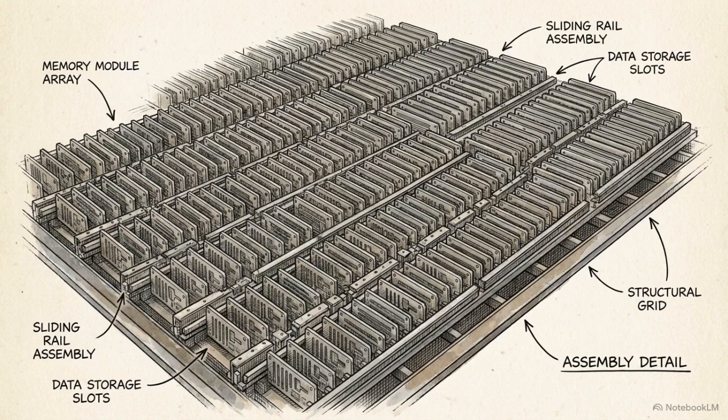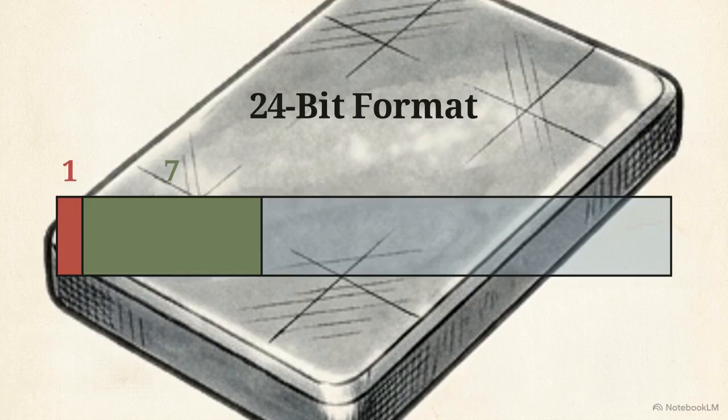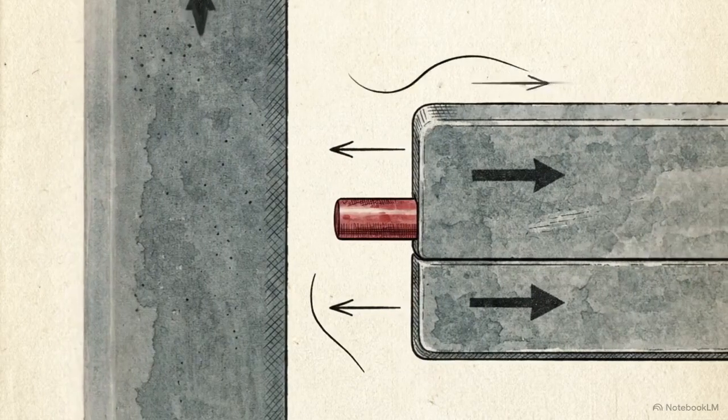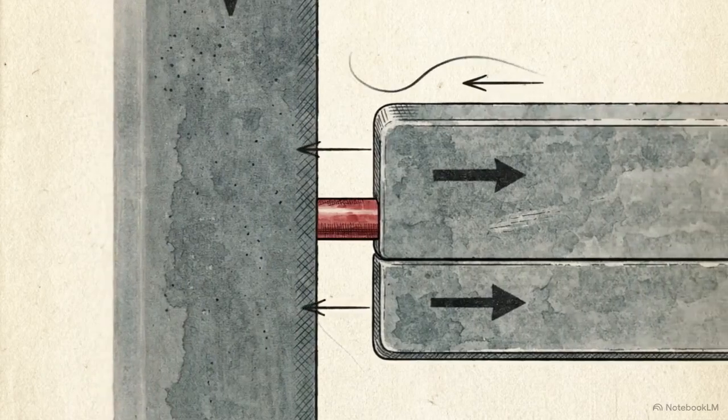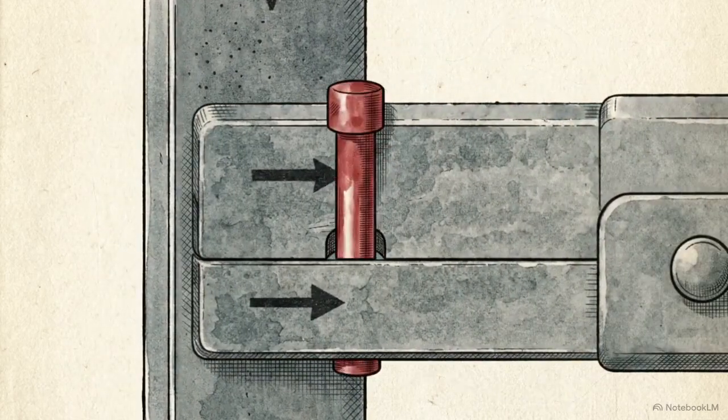Processing logical operations is only half the battle. A computer needs an addressable place to store the results. This block diagram shows the Z1's memory architecture. It stored values in a 24-bit floating-point format, strictly dividing the memory into a sign bit, a 7-bit exponent, and a 16-bit mantissa. Reading any stored bit required a vertical plate movement to mechanically select the data point, followed by a horizontal pulse to extract the actual value.